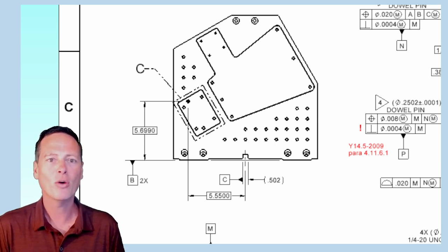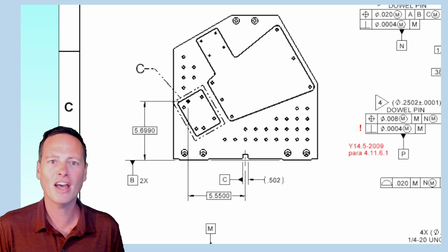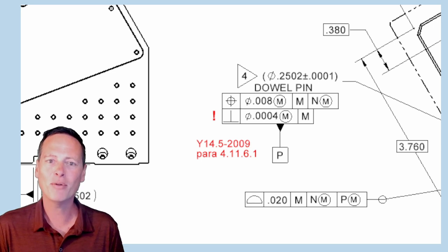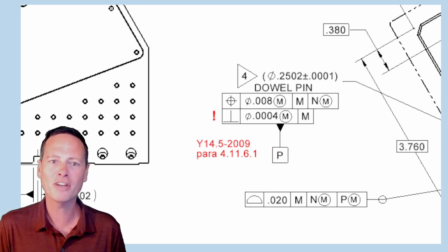We can't leave this pattern of features free to swivel around on the basic location of the first pin. We need dimensions that will define its basic orientation, and there needs to be a tolerance, some kind of tolerance, so we know what's acceptable and what's not. And another note, don't be thinking that you can just sprinkle a little magic datum B reference into this callout right here. That would put you in the area of the bogus datum reference frame if you saw my video on that topic. You do need to bring datum B into it, but there are better ways of doing that.